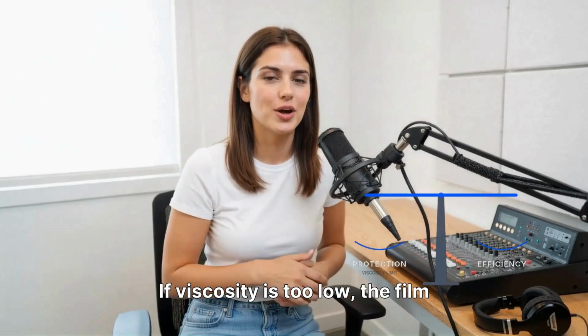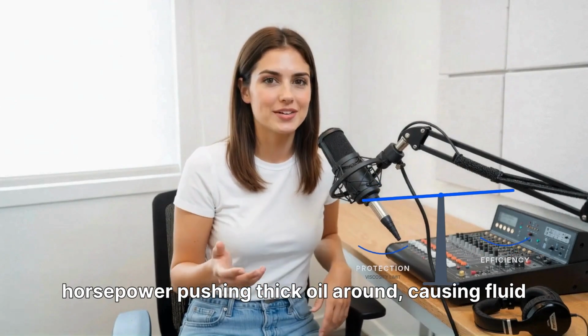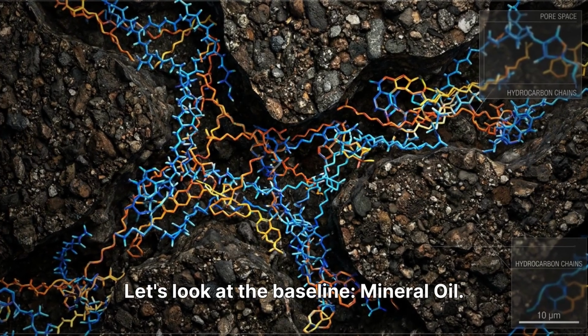If viscosity is too low, the film collapses. If it's too high, the engine wastes horsepower pushing thick oil around, causing fluid friction. So how do we get the perfect fluid? Let's look at the baseline.